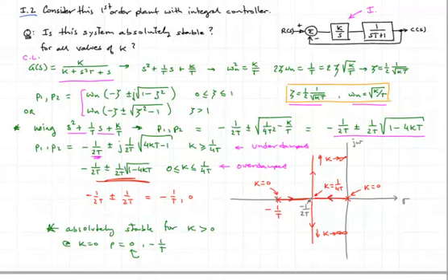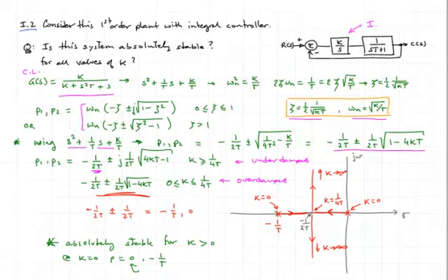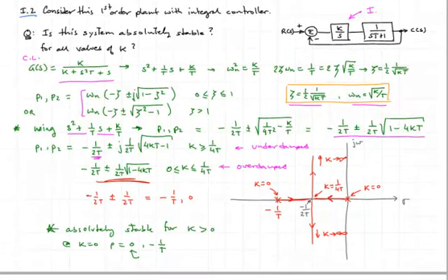Okay, so the root locus technique that we're going to learn is going to allow us, through a manual, non-computerized procedure, to sketch initially, qualitatively, but to varying degrees quantitatively, the locus of roots on the s-plane, including knowing whether or not that locus of points could land us in the right half s-plane, and thereby produce an unstable system.